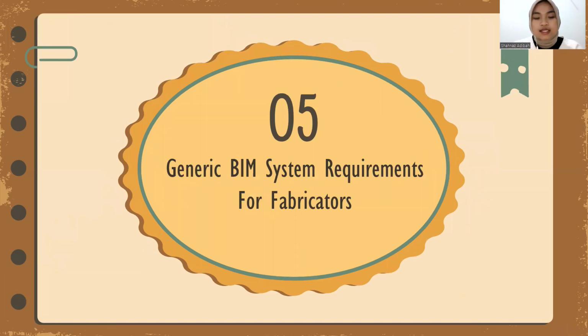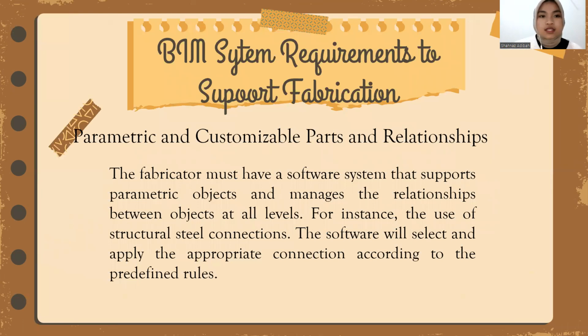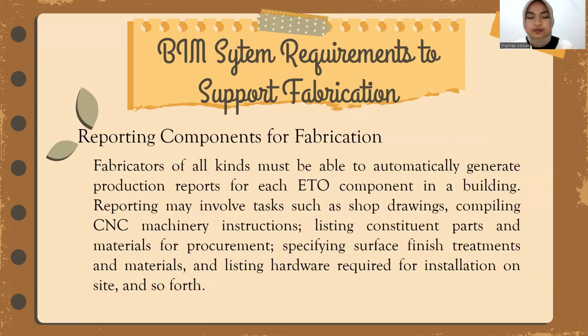The fifth section is generic BIM system requirements for fabricators. There are several requirements for the BIM system to support fabrication, including, one, parametric and customizable parts and relationships. The fabricator must have a software system that supports parametric objects and manages the relationships between objects at all levels. For instance, the use of structural steel connections. The software will select and apply the appropriate connection according to the predefined rules.